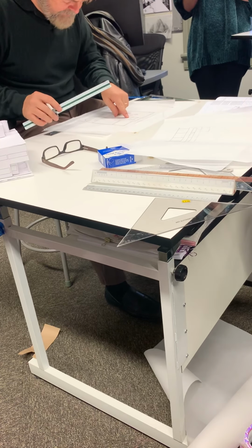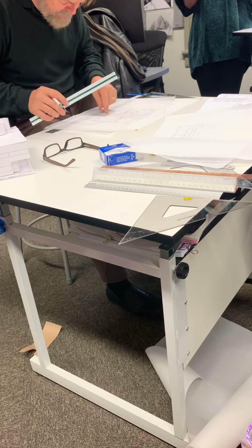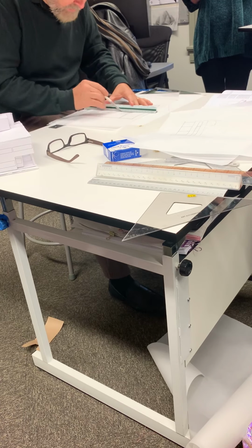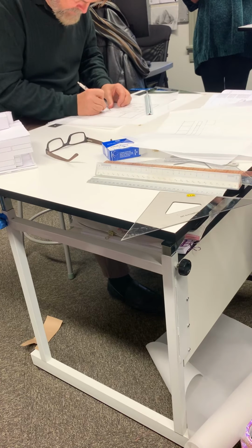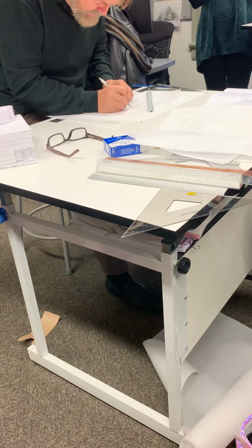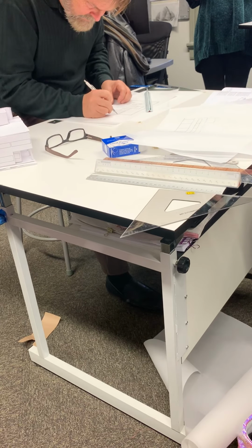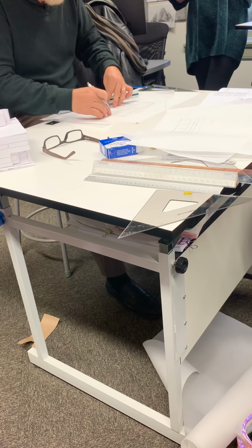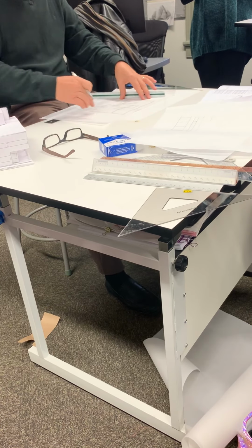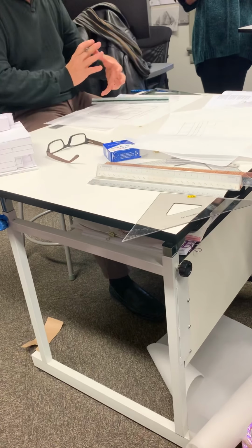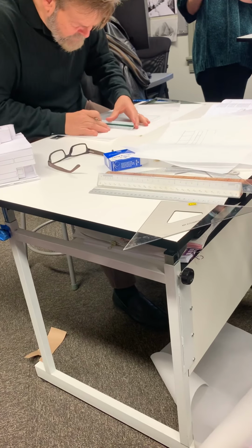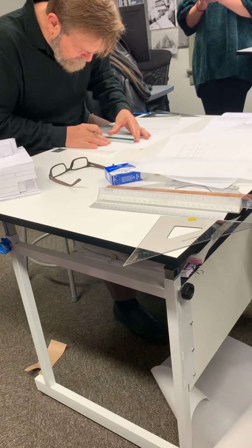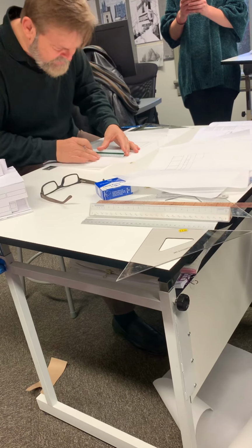And then I'm going to try and find this location here, where this is the wall, the hole inside, okay? So now I'm going to try and find where that is. How do I find that? I've got to come from the corner. Remember, we always reference from the outside, okay? And then the 1/8 inch scale tells me that this location is 17 feet 6 inches.